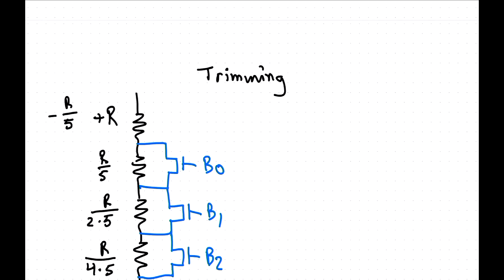It does, of course, add some parasitics, so you get some capacitance in these nodes. You need to make sure that the on-resistance of the switch is much smaller than that resistance there, so it becomes big. You can also do a series component, or you can put these in parallel instead, and then switch them in and out. It's kind of the same thing, really, but the parasitics are a little bit different in that case. Normally it's a static thing. Does that answer your question?